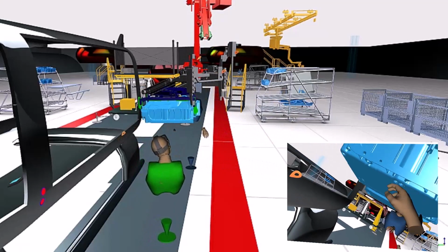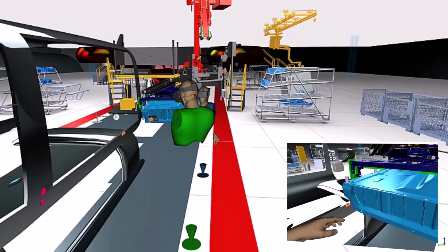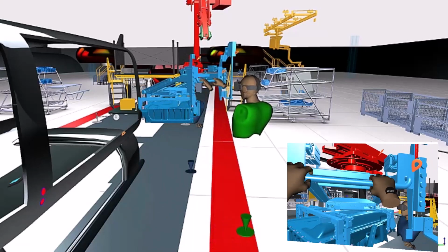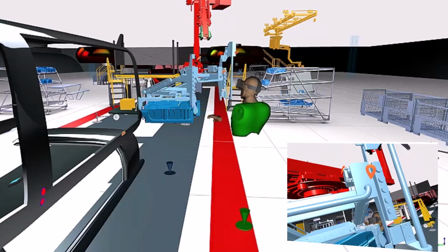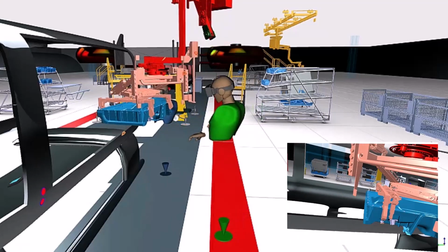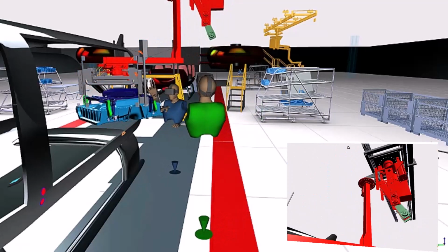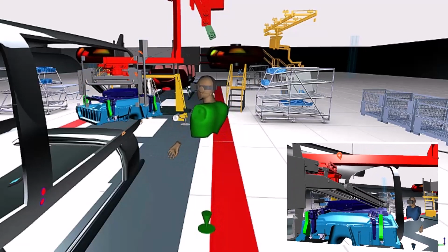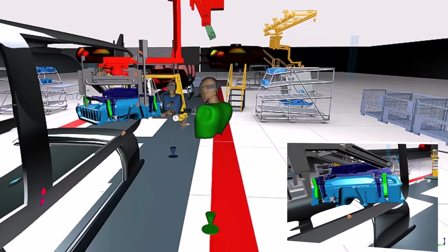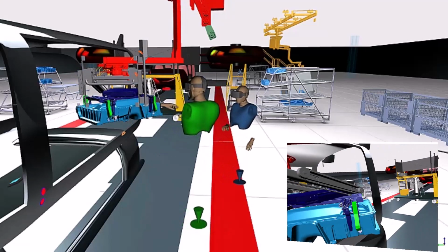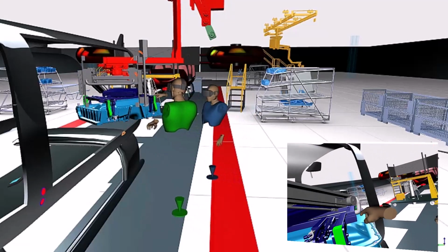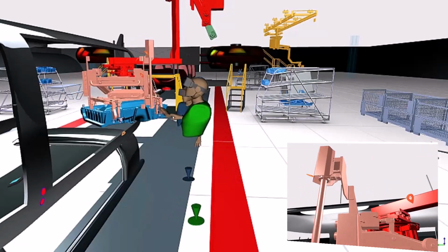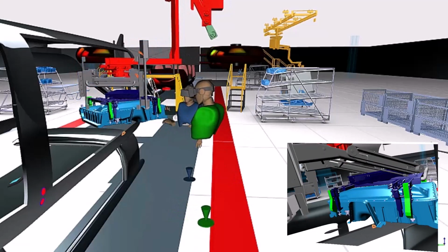In addition to validating the procedural order of assembly, it is also necessary to validate the tools, that is, these products that we buy that help us build our initial product. And so this tooling may be an overhead hanging gantry crane, an assist lift device, something that's going to help me assemble this vehicle. So in this case, we're loading one of those large batteries into this electric VTOL, and we want to validate, is this tooling safe and appropriate for us to operate?